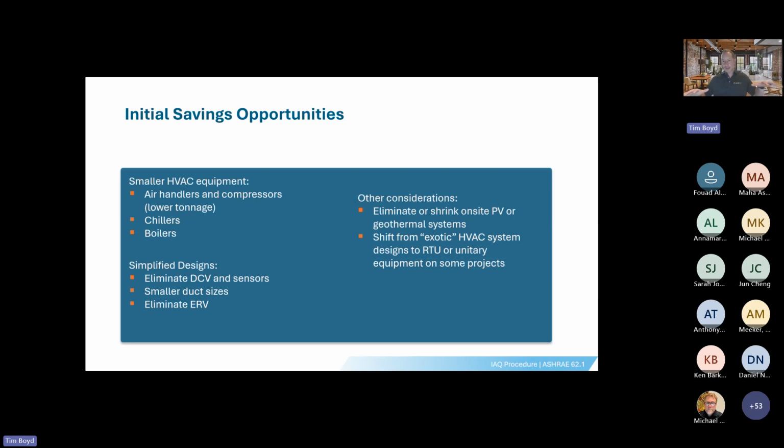A job in New Jersey had a building that was 18 or 20 stories tall, but the first floor was being renovated into a private school. The louvers were in the transom above the door for the original design of that building. When the engineer did the calculation, they said, I'm going to need to expand that louver to bring in more outdoor air to meet the requirements for this school. What they were going to need was to either knock out a door or a wall, creating a huge loss of space in an inner city school where space is at a premium.